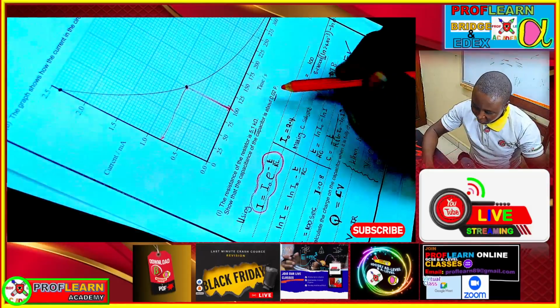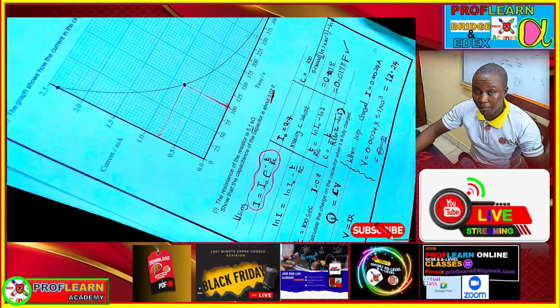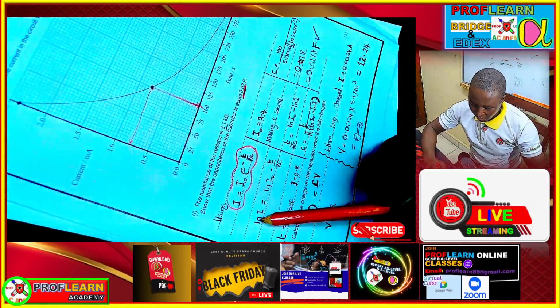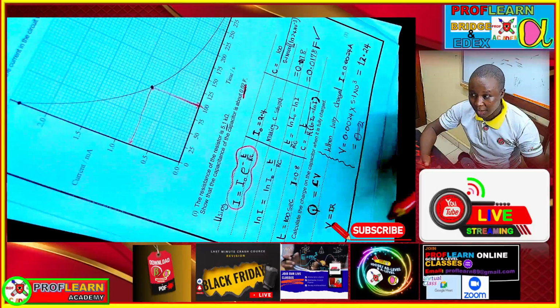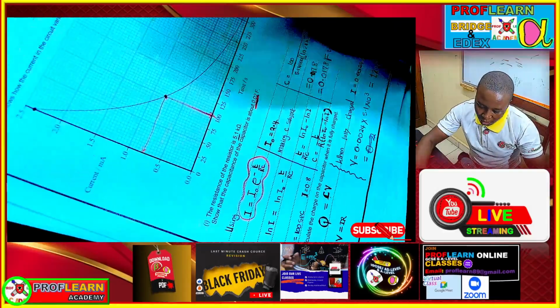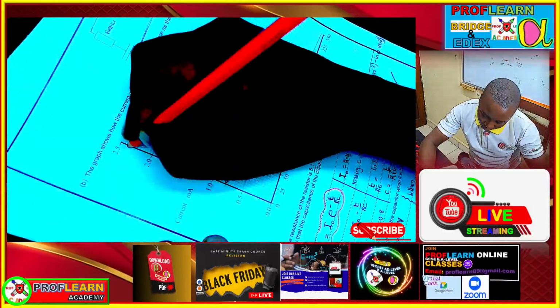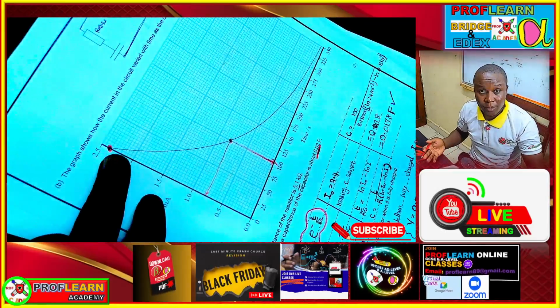Remember, the purpose is to find the capacitance, and the capacitance is the value of C that we are having here. So if you introduce natural logs here, you have ln of I, the current that is remaining, to the ln of the original current, and I naught is the current when time is 0.